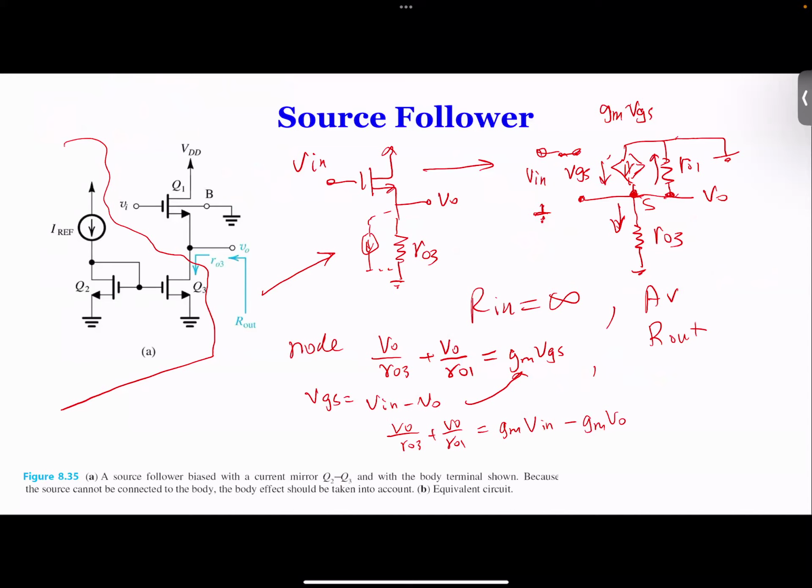Remember, we derived this circuit, and we find out that only output resistance matters because the gain is almost 1. Only the output resistance here, which means this part doesn't matter, only the resistance over here matters. Yeah, with internal resistance, the early resistance. With the small signal model, it will tell you that only that early voltage, early resistance matters,